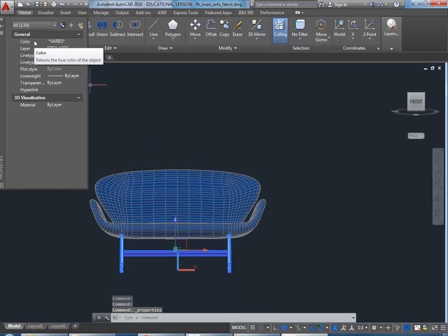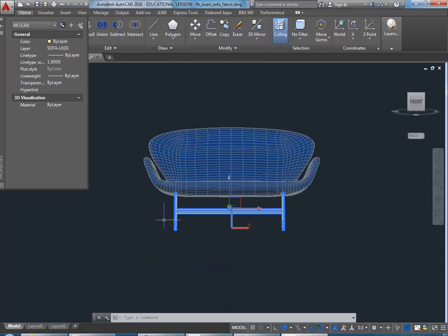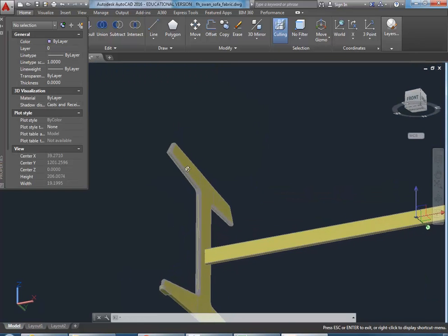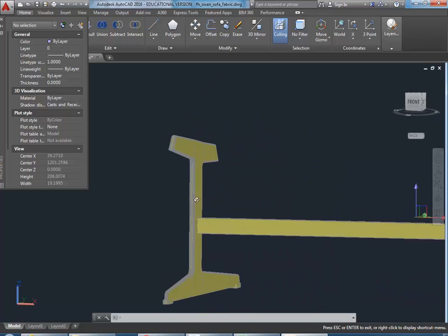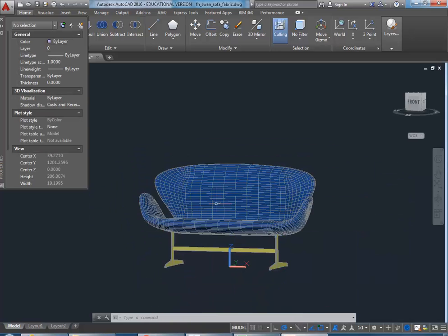So I'm going to right click and then go to properties, and you can see there the colour is set to, so it's not by layer. So I'm going to change that there to by layer, and now they'll have the colour of the layer that they're on. Now, it's actually done, it's pretty good. Okay, it's selected all of the leg actually, so those at least are joined objects. So that's a nice, easy step actually.